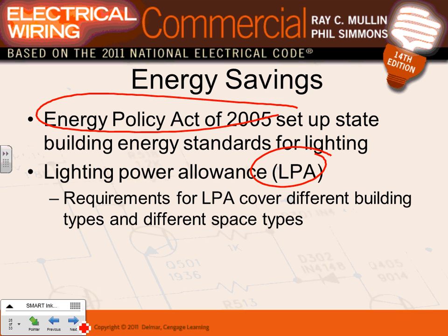And lighting power allowances. Lighting power allowances. You guys remember how? Anybody remember in the office? In the office, the code allows you 3.5 for lights, and the energy code allows 1. Was it 1? I think. ComCheck allowed 1 watt per square foot for the office versus the NEC code book 3 volt amp per square foot. So there's a gap between designing a system for safety and designing a system for energy. And our job, you and I, guys, or the engineers', is how am I going to design a safe system and at the same time efficient? That becomes, Jeff, the ultimate happy medium that you're supposed to achieve when you design these systems.